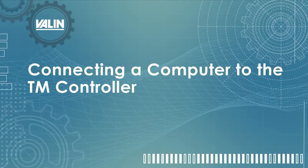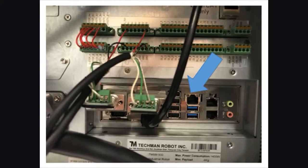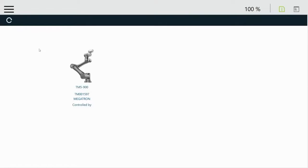You'll notice on the bottom of the controller there's some ports. There are 3 Ethernet ports there, and one indicated by the arrows where you're going to plug your PC into. Once you plug in, it uses DHCP, and after maybe a minute or two, you'll see the icon shown here.